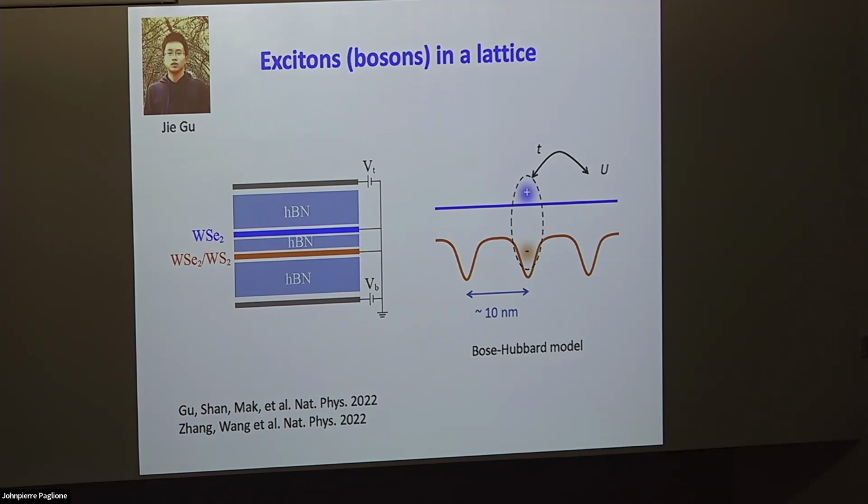But you can reduce that gap a little bit by applying the gates in such a way that you reduce the band gap. And typically that's what we do. You can reduce the band gap to about half a volt, and then the bias voltage you need to apply is about half a volt, which is nicer. It suppresses the tunneling if you don't apply that large a bias voltage. You can play with some of the engineering of the bands. So it's really a material choice and then applying the gate voltage to bring it to the point that you want. And there's a lot of experience in picking which materials to choose.